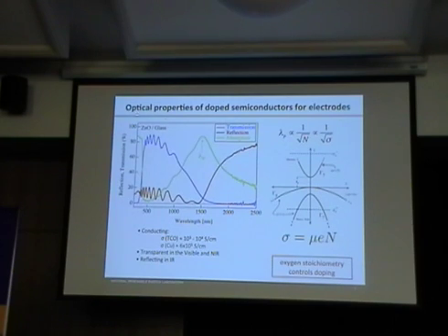So why is it we have basically this tail off here? What's happening? We have absorption. Well, yeah, so the absorption is in the green, so the absorption goes up, transmission goes down, reflection actually goes up after that point. So what's happening? This is free carrier behavior, right?